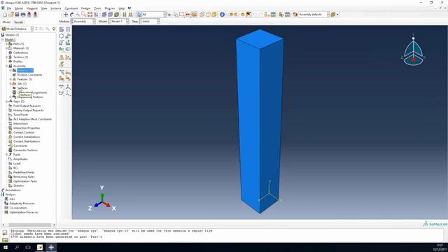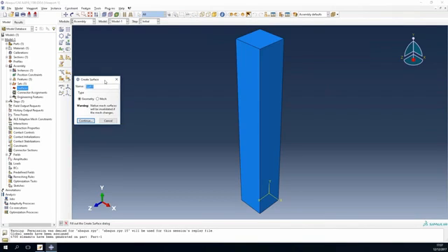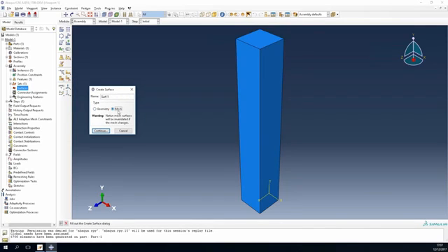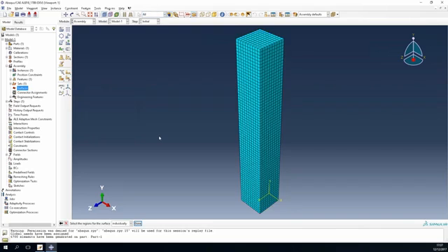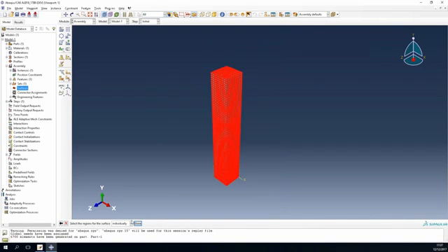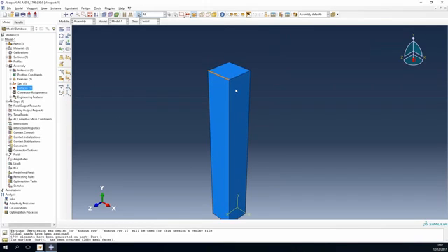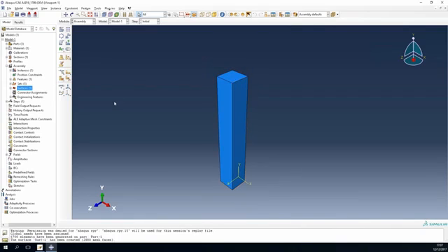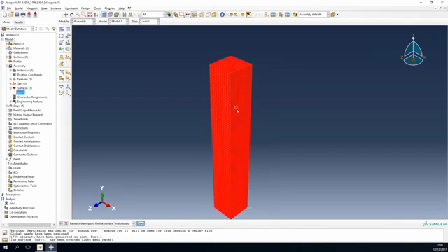So we have to define a surface, which is going to be our exchange of information. Okay, so I'm going to create one surface, and that is going to be a mesh surface, not a geometry one. Okay, because we're going to exchange information on the nodes of the actual mesh, and I'll select the whole geometry in this case, and of course the surfaces of all this 3D mesh are going to be the ones exchanging information with XFlow. Okay, so now I have my surface 1, which is the surface where we exchange data.